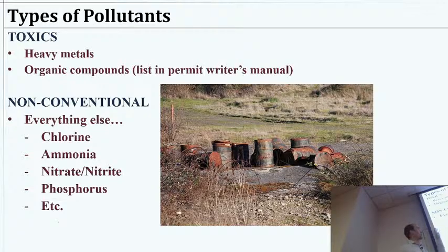Now, if we discharge that into a smaller stream or river, it could be quite disruptive because ammonia is toxic at several milligrams per liter. So if we discharged 5 milligrams per liter of ammonia and most of the creek is now, becomes 3 milligrams per liter because most of the creek is our wastewater, suddenly that kills everything. If I have those numbers right. I think it's 1.5 where it starts, we start getting something, but don't quote me on that. Not remembering at the moment. Either one of these could cause a problem, or maybe it's totally fine if there's enough assimilation capacity.